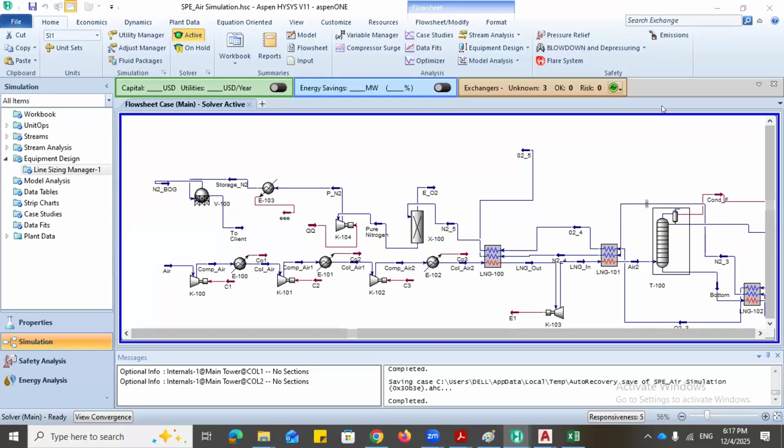So I saw a question. Ogbonna, try to ask your question where everybody is going to see it, so everybody will see your message. He asked the question: is the term boil-off gas appropriate considering the fact that the storage tank is of gas? This storage tank here, we are storing our nitrogen in a liquid form, right? But since we are storing our nitrogen in a liquid form, the dome, the top area, will not be occupied 100%. The storage tank will not be filled 100%. There will be a space, right?